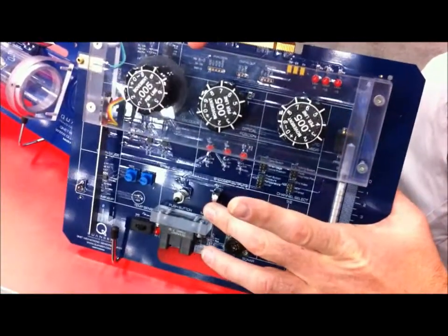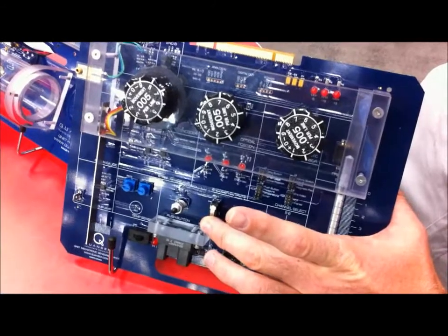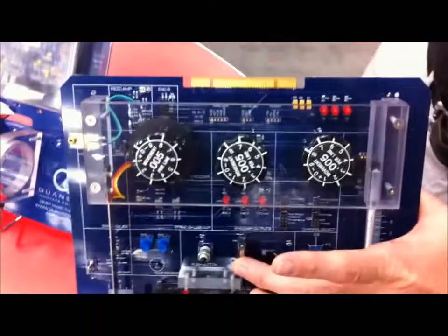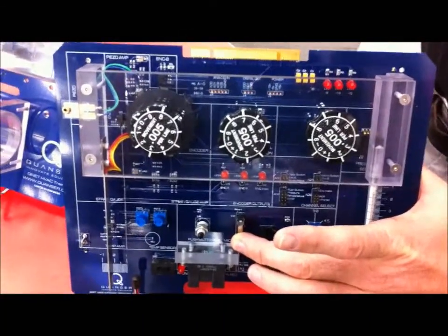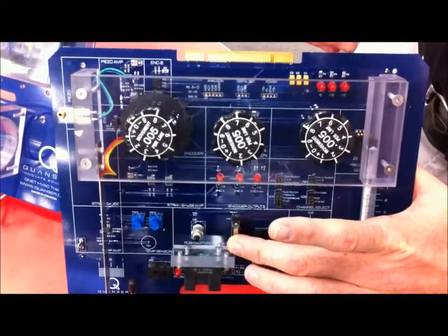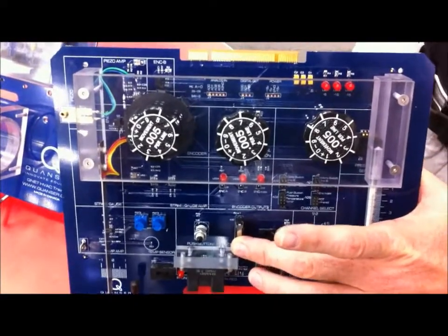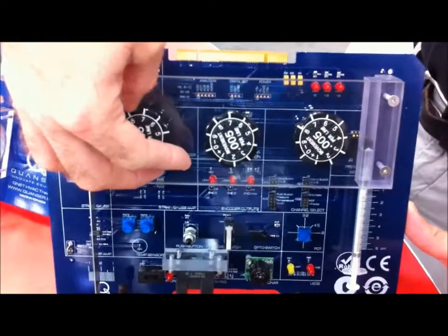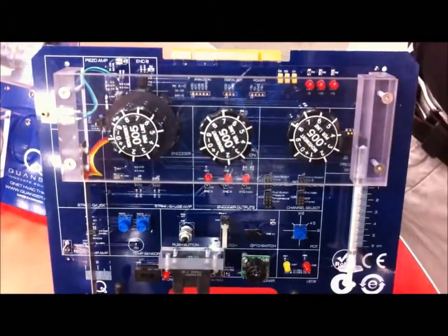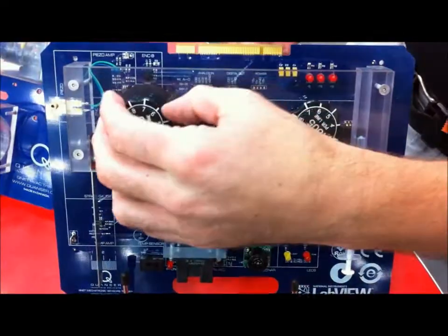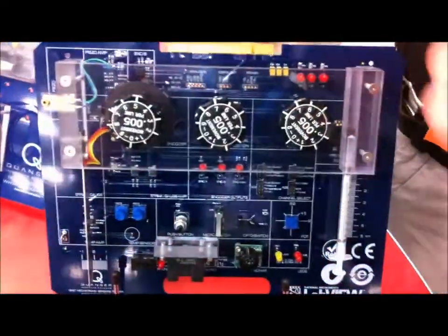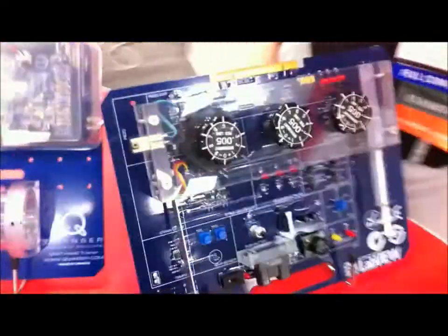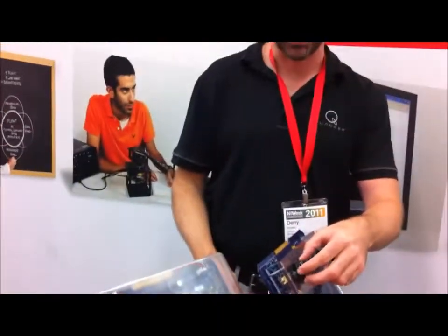You see it go from close to open to close in a very quick succession. The students would then have a challenge of writing a LabVIEW program in order to interpret that signal as a clean switch. The encoder module up here, you get the classic A and B 90 degrees out of phase signals, and they have to now write a little bit of logic in order to increase and decrease the count.